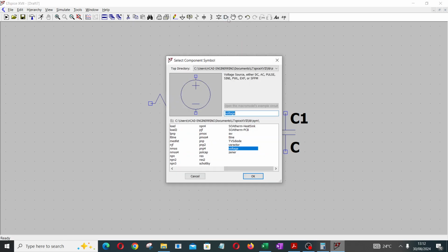So having launched your LTspice, you can see your components are already here. So we have the resistor. When you click on it, you press Ctrl R to rotate, then you drop it. You go and click your capacitor, then you drop it. Then the next one is to pick your voltage source. You go to component and you click on it, you type voltage.